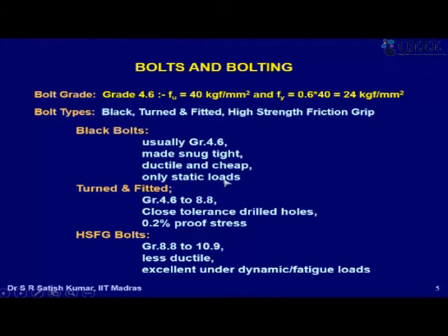But they are recommended only for static loads. Static in the sense of very slowly applied loads. So you may have wind loads or live loads, but these are all considered as equivalent static loads, so we can use them. We should not use them under dynamic or cyclic loads. For example, we can't use them in railway bridges, where when a train runs at high speed, the entire bridge may be shaken. At that time they come loose, the nut comes off, and sometimes they don't work well.